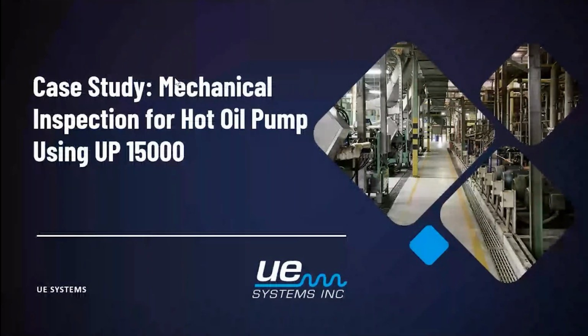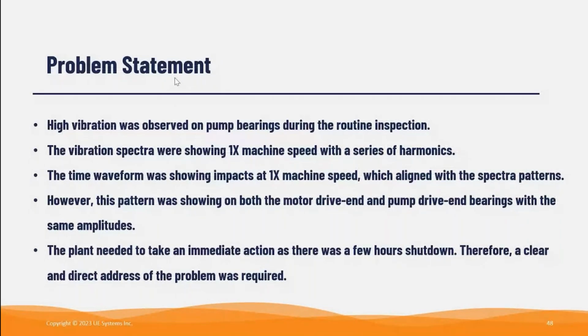The second case study focuses on detecting mechanical issues within a hot oil pump. So high vibrations were observed on the machine bearings during the routine inspection. The vibration spectrum was showing 1x and harmonics, and the time waveform was showing impacts at 1x as well. This pattern was observed on both motor drive end and pump drive end bearings with the same amplitudes, and the plant needed to take an action as there was a few hours shutdown only.